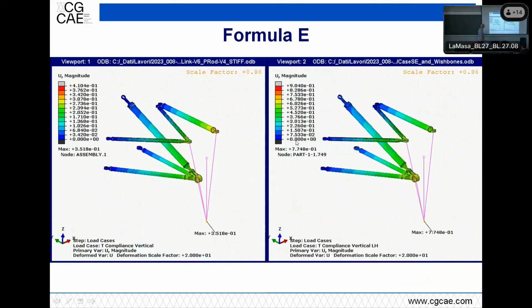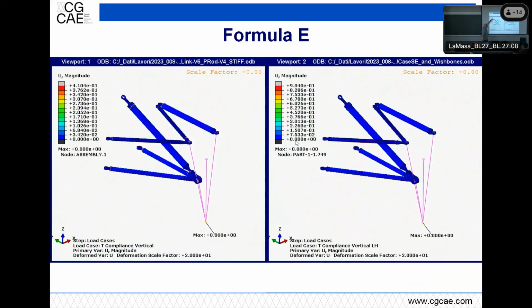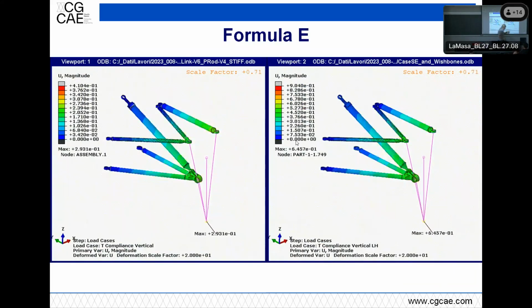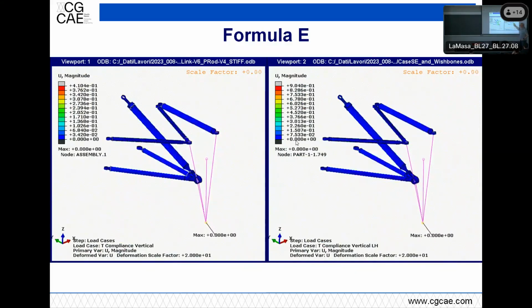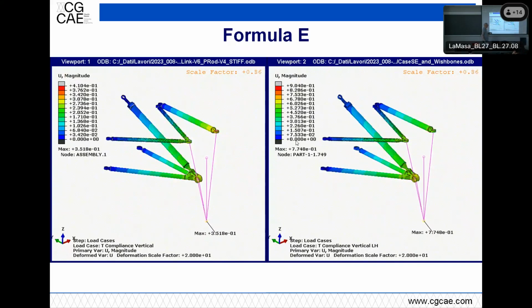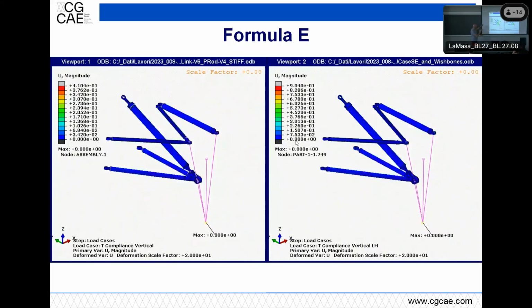And what we see here is the comparison from just the vertical load with the fixed model, so considering that those points are constrained to ground, compared to what we have with the super element. And you can see that, well, maybe it's not really that visible, but if you check this point, for example, you see it's moving quite a lot. The scale factor is 20, not really a lot in absolute sense, but enough to affect those camber stiffnesses that we were discussing about. So this suggested to modify somehow the drawing, the design of the casing where this is attached to stiffen that point up.